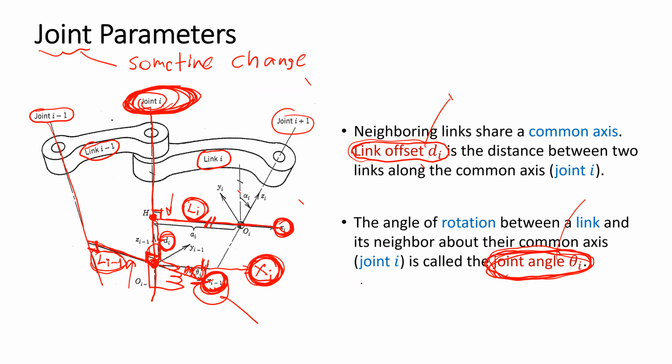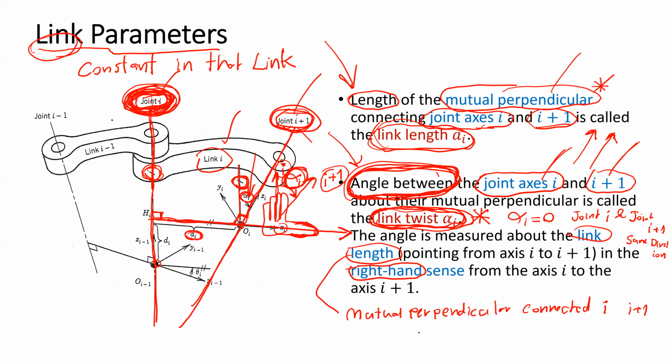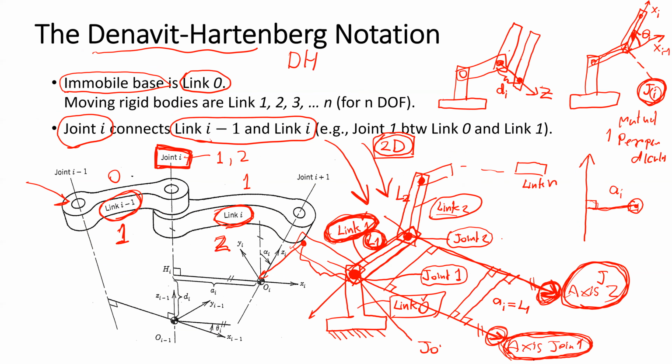If we look at our picture, we have joint 1 here, right? The axis of joint 1 points outward from the screen. So the z direction is also in the same direction as the joint axis, but the number will be one step less than the joint number. So this will be the direction of Z0. This will be the direction of Z1 at joint 2.